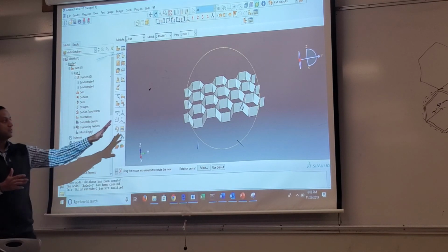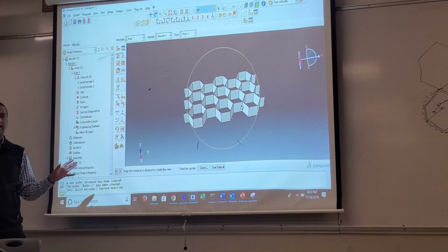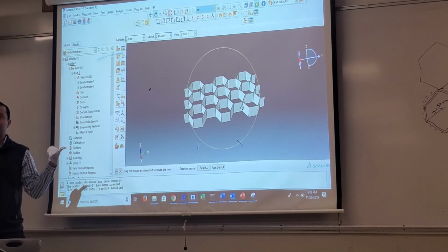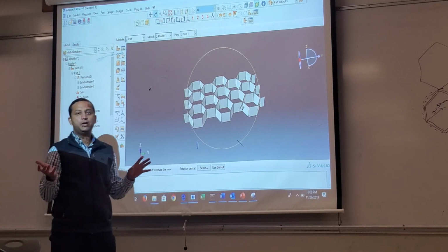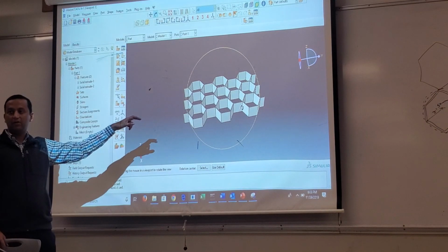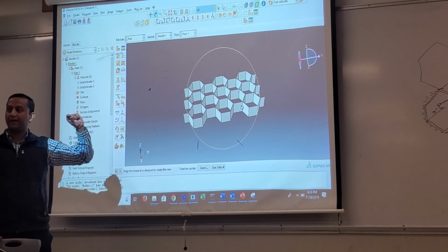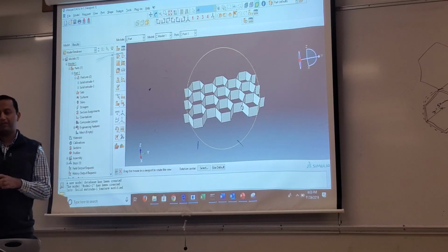Yeah? Once you get that, I mean, you have got 50% of the job done. Now you follow with me. So this is part 1 done. Part 2 will be a flat plate, flat composite plate that will go on the top and the bottom. So what you will be doing is an impact simulation, but not having this cell with you. So I'm going to create a flat plate, composite plate, you are going to create with me. Now I'm going to create a steel ball, you are going to create with me.